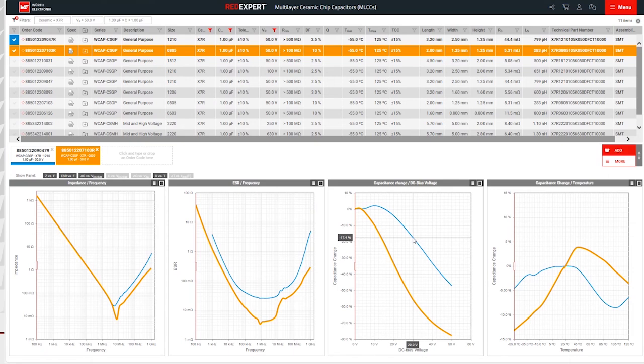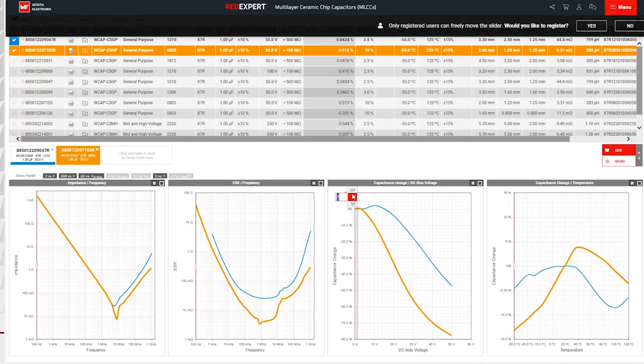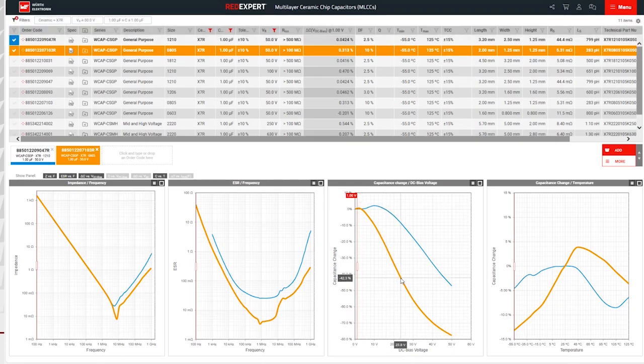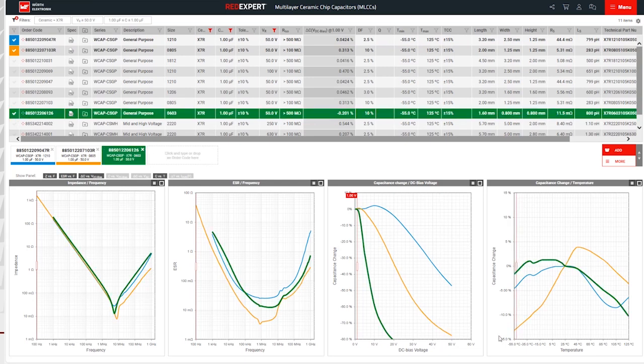Same dielectric, same voltage. At the same voltage, you will drop now at 24 volt. I try to put the 24 volt exactly here. Oops, my cursor is not working. I will try with this one. It will drop in the same value already 42%. Now, what is your expectation if the sales guy tells you use 0603? It's still perfect. I will choose now 0603. Already at 20 volt it has dropped more like 80%. So from your 1 microfarad, you have only 20% left.